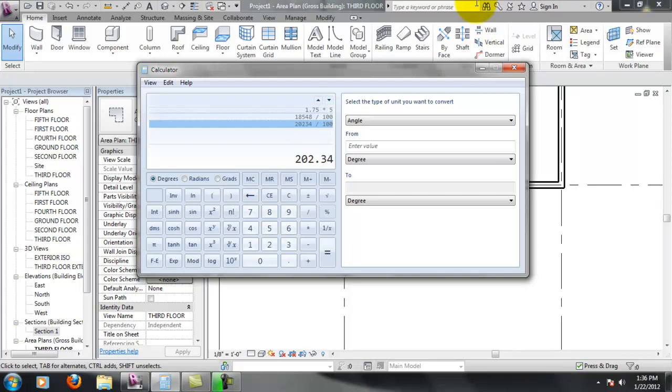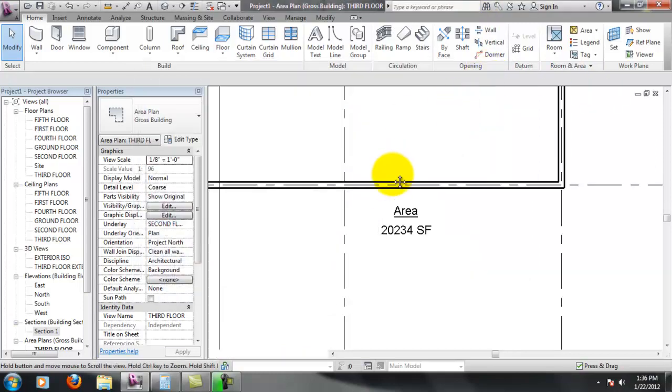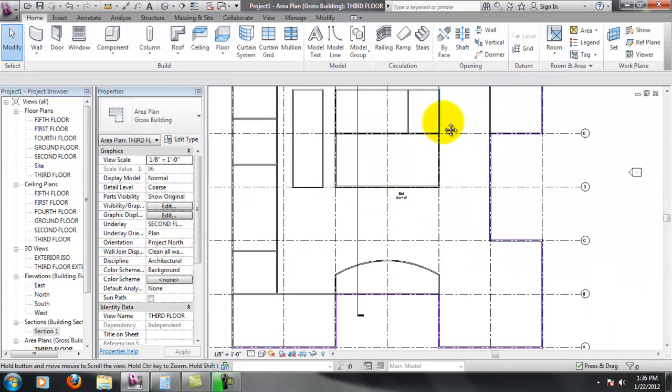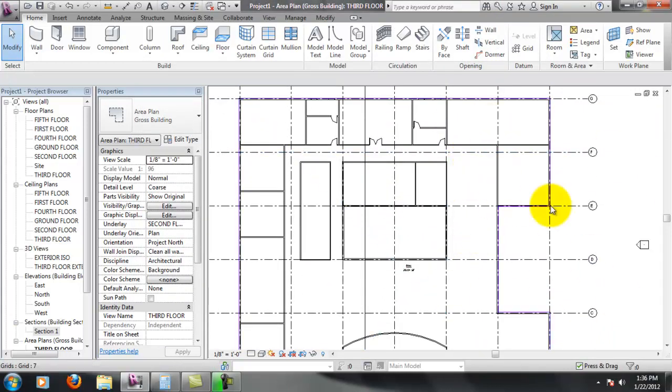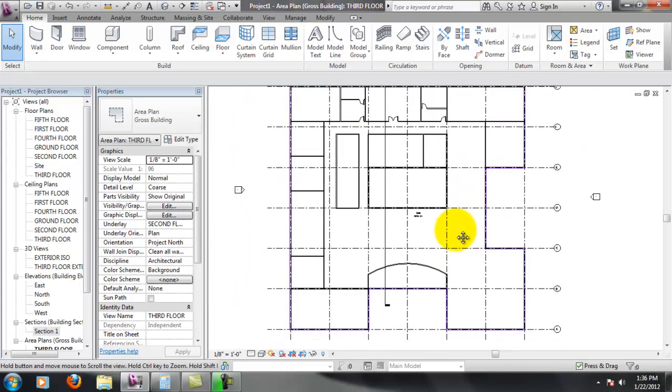And that's our occupant load for the 3rd floor. Now, this number can change too. If you've noticed, what we haven't included in this floor yet is a stairway, and we'll include a stairway later on in some portion of this, probably back in here. Usually in a corner or so is where you'll find the stairway.